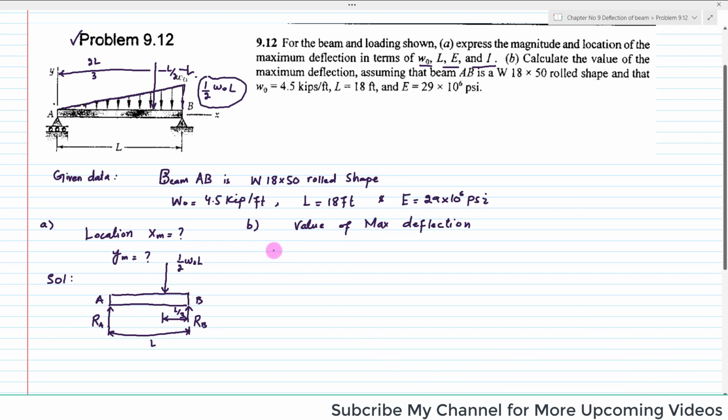Okay, so using the equilibrium conditions, we have the sum of all forces along the y direction equal to 0, and there is another equation, the sum of all moments equal to 0. We will use these equations in order to find the reaction forces A and B. So from the first equation we can see RA plus RB, because these two reaction forces are upward, minus 1 over 2 W naught into L is equal to 0. So it means that RA plus RB is equal to 1 over 2 W naught into L.